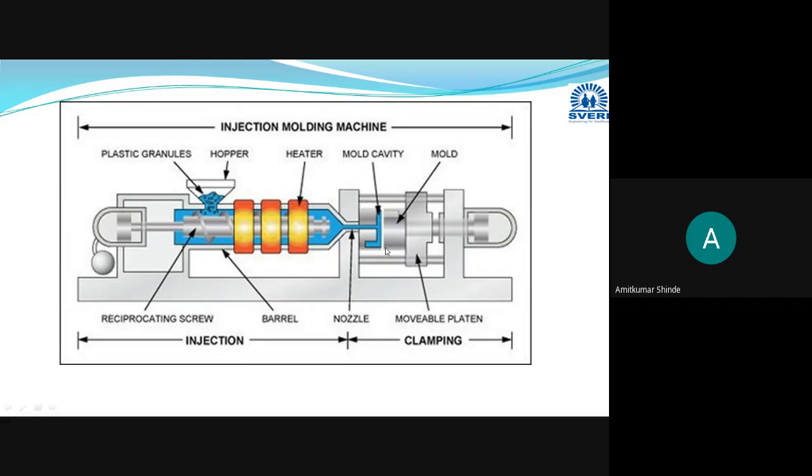It is ejected with the help of one ejector mechanism. With the help of that ejector mechanism, we are going to remove that manufactured component from the mold cavity. First you have to remove the movable mold part, and after that, with the help of the ejector mechanism, we eject the manufactured part from the mold cavity. You have to take proper care that the component should not get damaged here. So after the ejection from the mold cavity, we will obtain the final product.